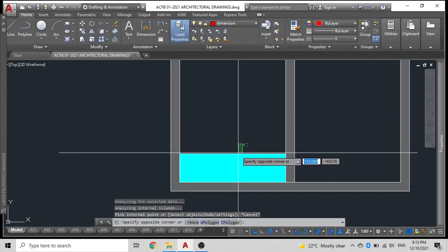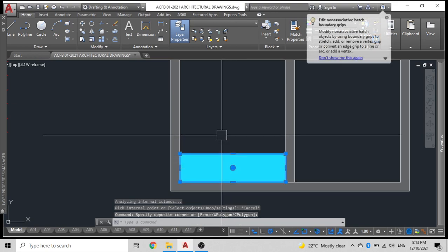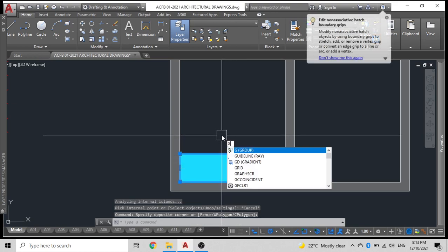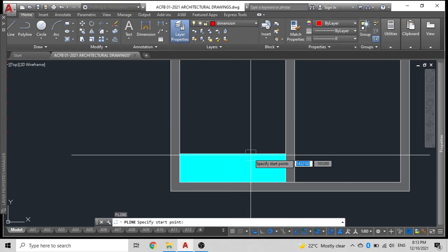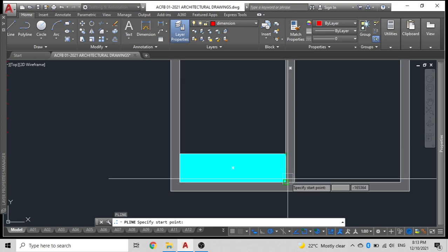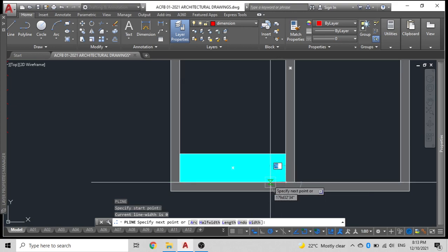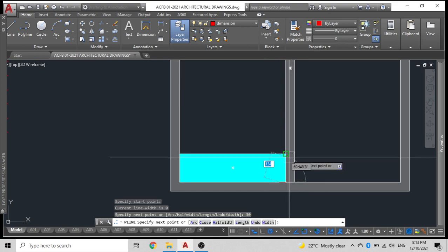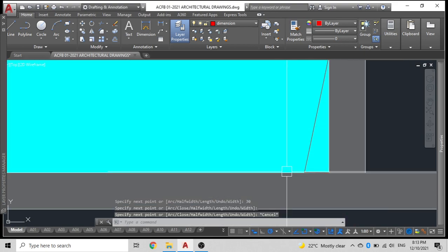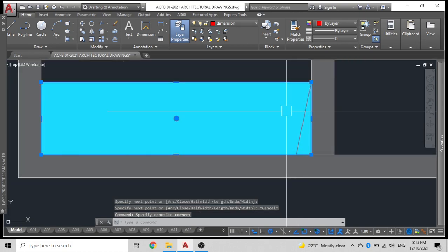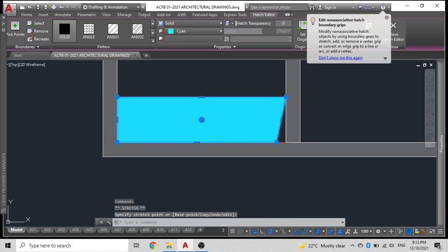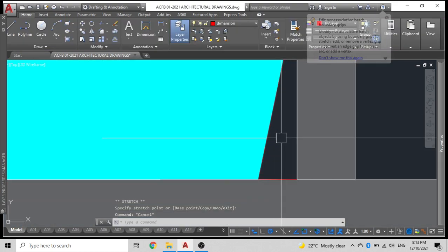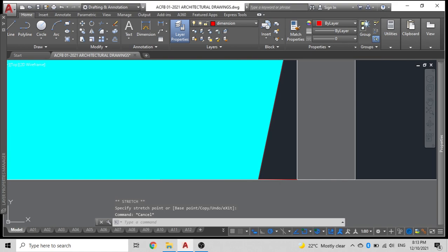Now we're not done there yet. So what we'll do is basically we'll select both of those, then we type G for group. My apologies. We'll type a polyline, then we do that. The first line that I'll draw will be from this point to this point. That's somewhere up to 25 to 30 mm like so. Then I'll make that line over there. I'll continue that line to the top. Then I'll select the hatch and move it in like so. And I'll put another hatch inside here. Type H for hatch, then press enter.